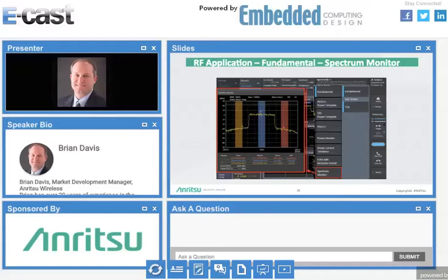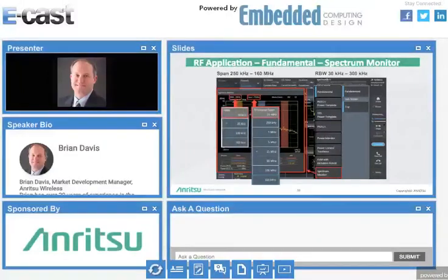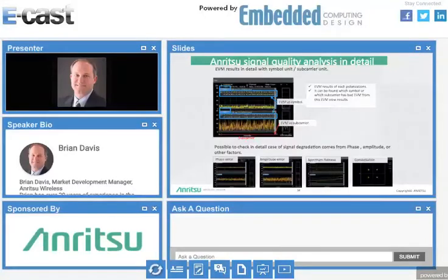And then just skipping down to spectrum monitor. We've got just a general purpose, nice spectrum monitor in there. You can put in markers, you can change the frequency span, just kind of a quick and dirty measurement there. You can change the resolution bandwidth if there's some strange spurs you're seeing in your uplink. It's not meant for out-of-band emissions testing, although this equipment can do it, but you really need a wider spectrum analyzer, signal analyzer to do those kinds of out-of-band measurements.